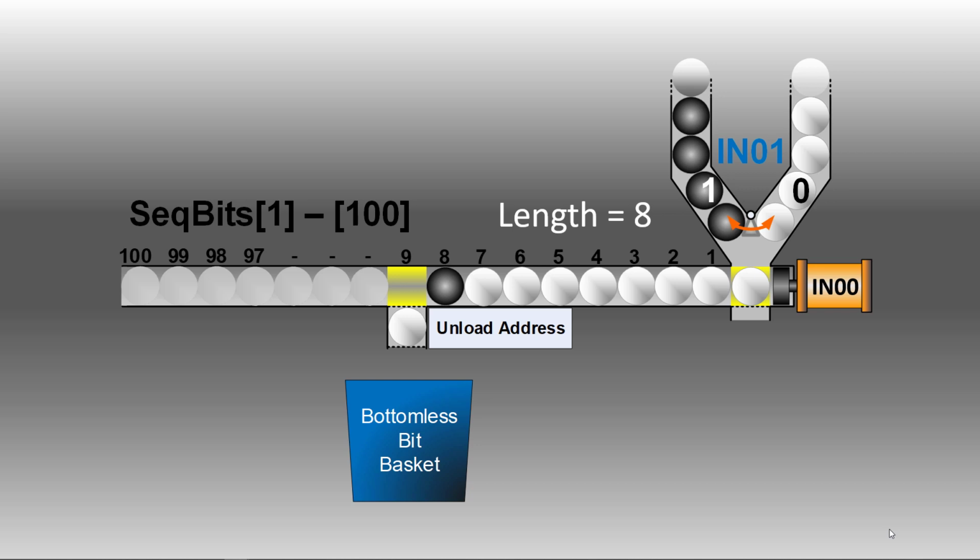That's in RSLogix 5000, Studio 5000, and RSLogix 500 with MicroLogix SLC 500s. But with the Micro 800, it's considerably different. It's the same idea of shifting bits, but you have some restrictions as far as where you can shift the bits or in what data types.